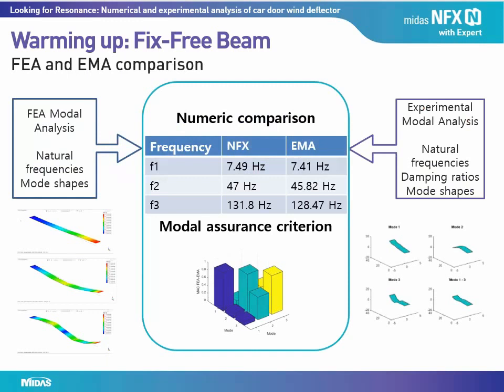Now we have two sets of data. One is obtained by midas NFX. The other is from the experiment. We can compare them in different ways. Numerical comparison in this table shows natural frequencies obtained by NFX and the test. Good agreement is seen. This is indeed expected for this simple structure.